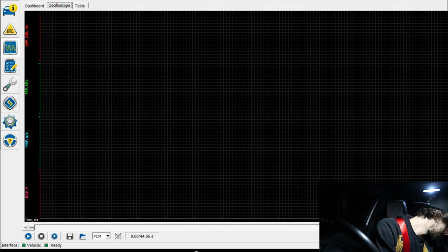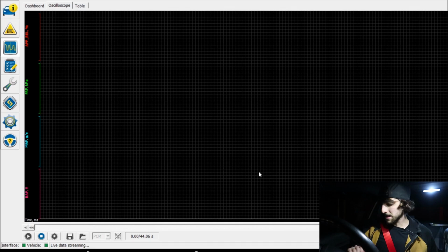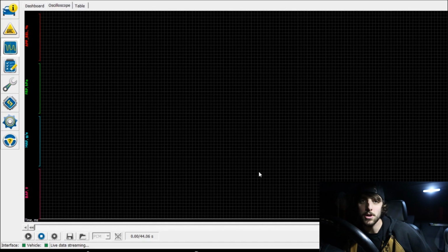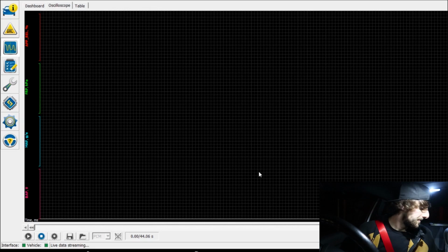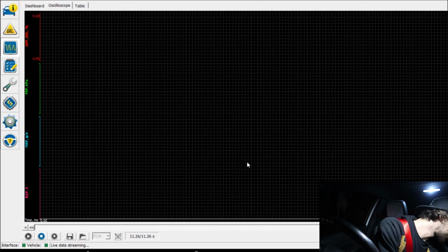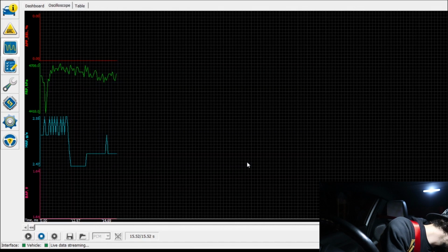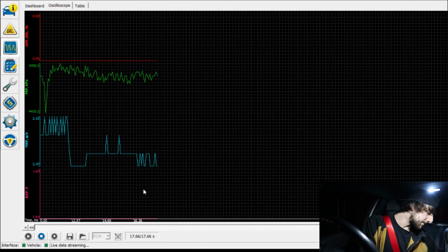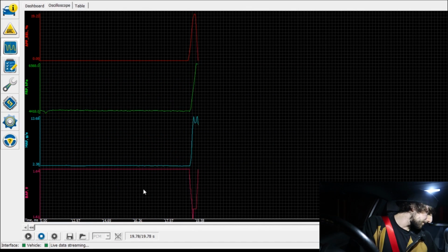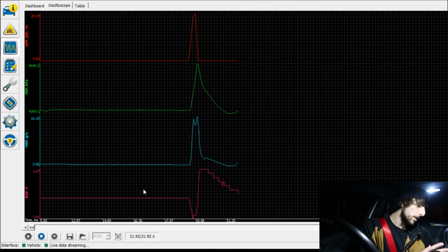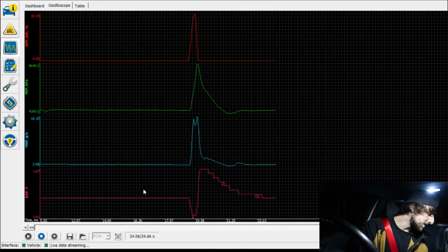you will find, once I press play down the bottom, so obviously it's making sure that I've set my switch back across to the original position. So I'm going to click that across now. And then once I've done that, I'm going to press OK. And here we go. So currently you can see that my MAF airflow sensor is going a bit weird. But if I was to accelerate, you can see all the peaks go up with my acceleration.